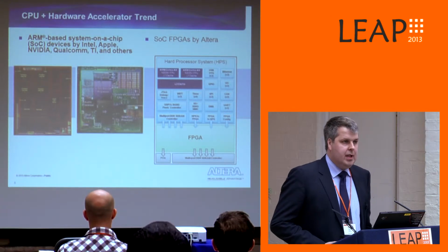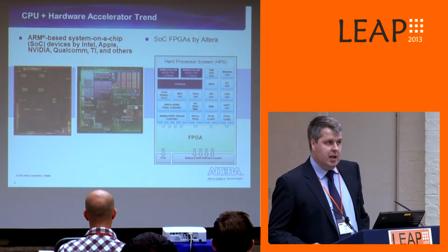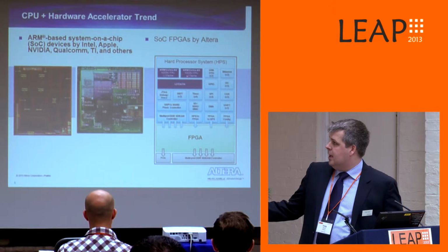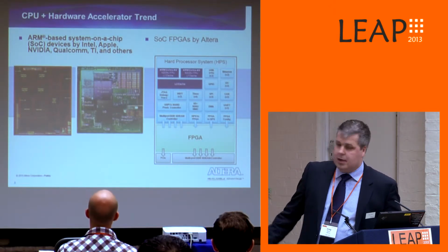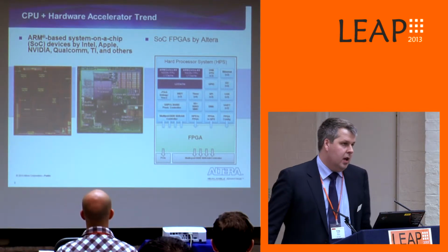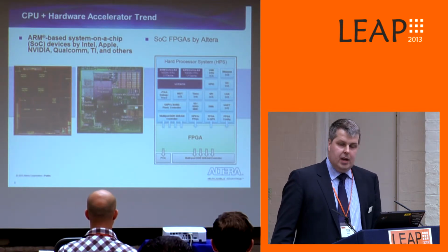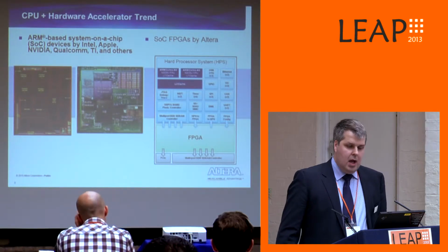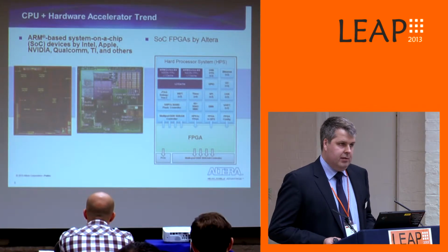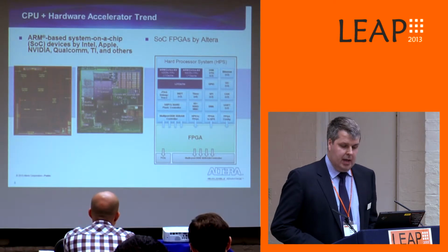So we have a variety of FPGAs, our Cyclone 5 and Arria 5 SoC products, that are built on a 28 nanometer low power process, so a low power solution, that has within it a dual ARM Cortex A9 processor subsystem and a set of peripherals with massive amounts of connectivity to the FPGA fabric to build a very high performance computing system. And there you're going to use the benefits of the FPGA fabric for acceleration of application areas and the processor, where the processor works well for a lot of decision-making logic and things like this.